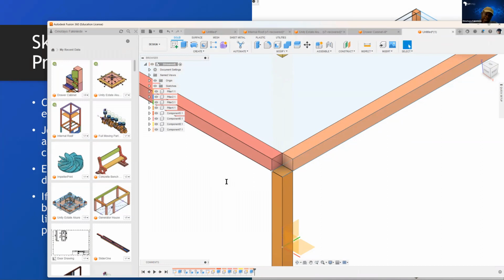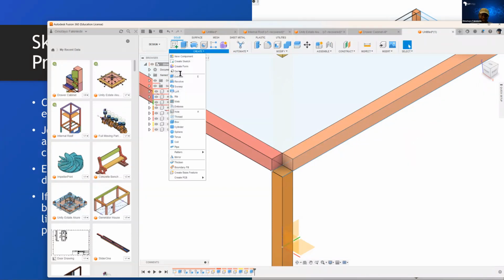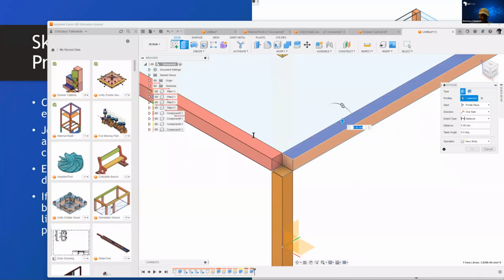What I'm going to do next is to extend the pillars up and then create the walls, both up and down where they exist. If there are no questions, I'm going to come here and extend this pillar up. And I do that as new components for all the pillars around. But before that, it may even be nicer to create the walls. So I can say create extrude. Let's see if I create this one as a profile and create, okay. If I create that, and then the distance again, this one now, let us say 5,800.